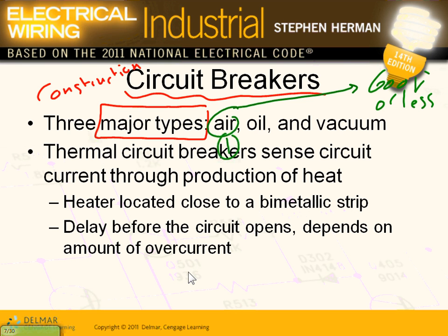The second one is oil circuit breaker. Oil circuit breaker, as the name implies, guys, when they interrupt in a tube that's full of oil. That's all. They have a tank full of oil, and we have a short circuit. When they interrupt the short circuit, the contacts are immersed in oil. Anybody can tell why they put it in oil? Oil will extinguish the arc. A huge arc will come out of it, and the oil basically will kill the arc.